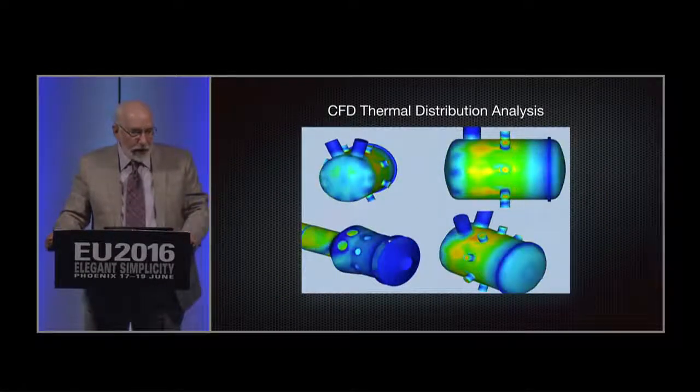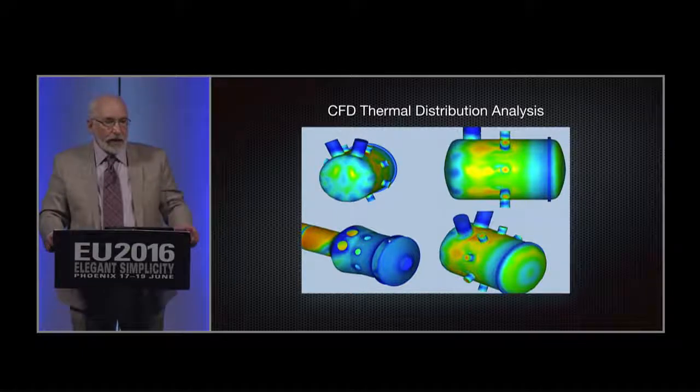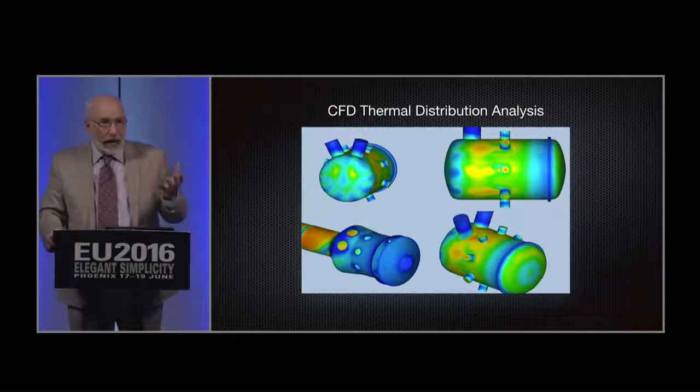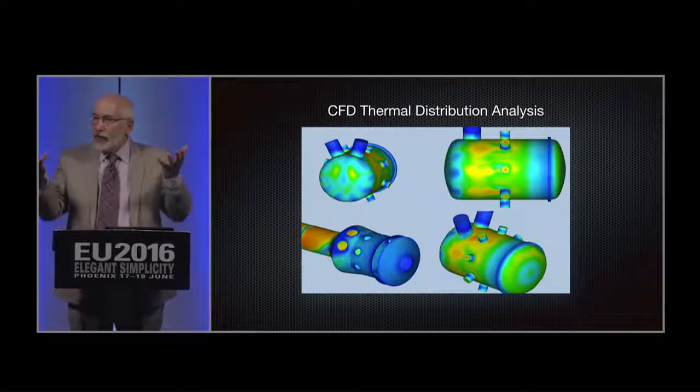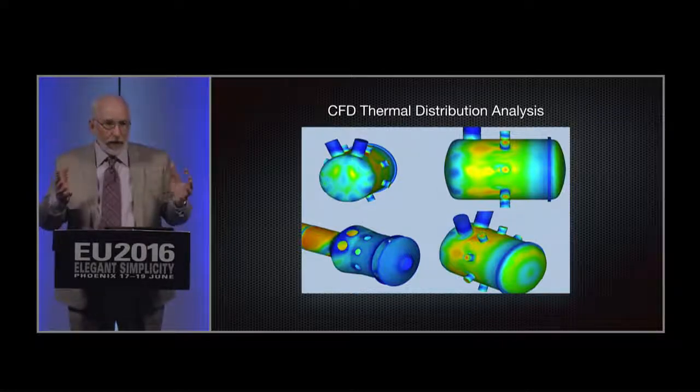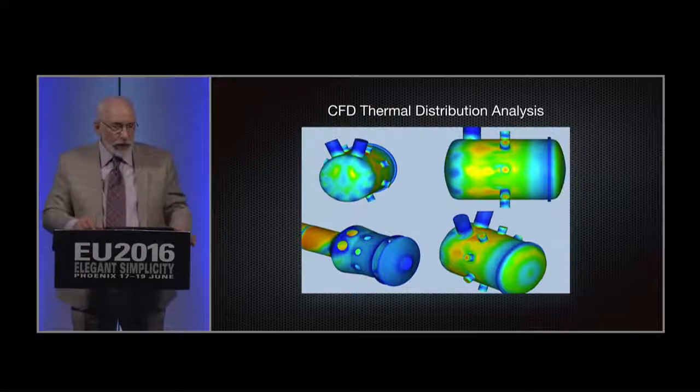And this is some of the thermal distribution, and it's a lot more even. So we're not getting 500 degrees now. If I can get a fan to pull air over the surface, we can bring the chamber into stability at around 100 degrees Celsius. Now that's something that we can work with. It's still going to boil water, but the worst case scenario is about 100 degrees Celsius. It's not going to melt gaskets. Yes, you could fry eggs on it, but it's workable.